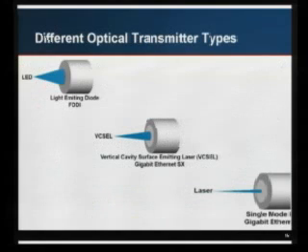So here's kind of a size comparison, and something happened to my picture and it got cut off on the bottom there, but it shows old LED transmitters, the modern vertical cavity surface emitting lasers, which you might see in an old Gigabit SX, that kind of thing, and then anything that's an actual laser, which would be long haul single mode optics. It kind of gives you a size comparison of what width signal you're sending.